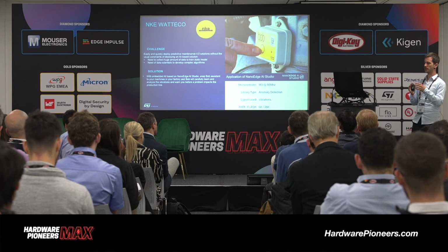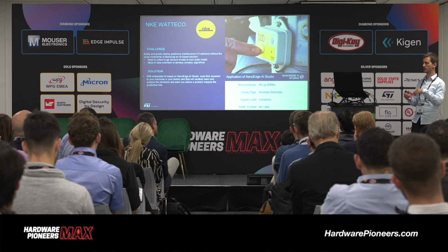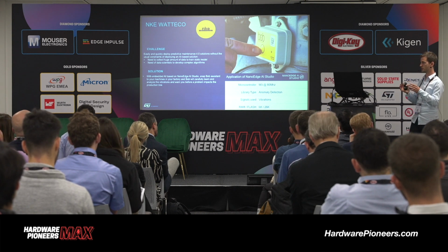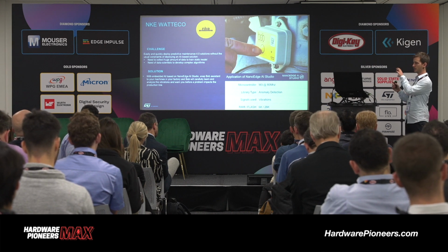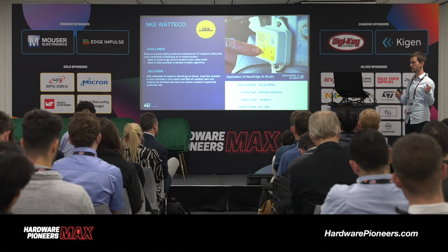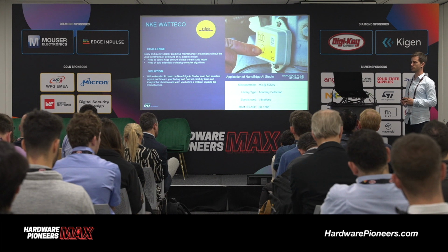No, because it's not weights like you would imagine in a neural network, right? It's much more general than that. You can have decision trees or SVM or any other machine learning model. So in that sense, no. But really, the knowledge is just a bunch of numerical values somewhere in RAM. So you can extract these weights or this table in C language, put them somewhere in the flash memory, and transfer it to another device that has the same library, to bring the knowledge that was learned on one device into the new device. So there are ways to do that, and we have a tutorial for that as well on st.com.